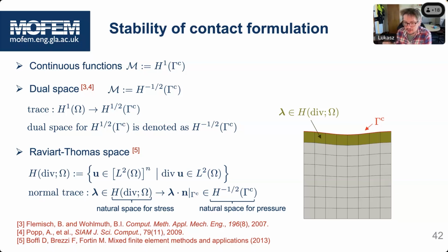Yeah. In that case, we have arc length control. With arc length control, the user prescribes the amount of crack area which should be grown in one load step, and the load is adjusted to satisfy that criterion.